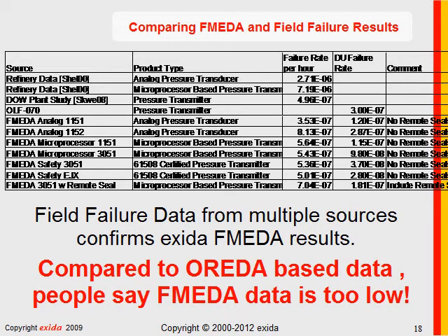And I look at the numbers for analog pressure transmitters, and I see numbers with a total failure rate running about 5 times 10 to the minus 7. And FMEDA results for 2 different analog pressure transmitters without a remote seal come out roughly 4 times 10 to the minus 7 to 8 times 10 to the minus 7. And you might say, what's the difference between those 2 designs? There is a substantial difference in the complexity between those particular designs.